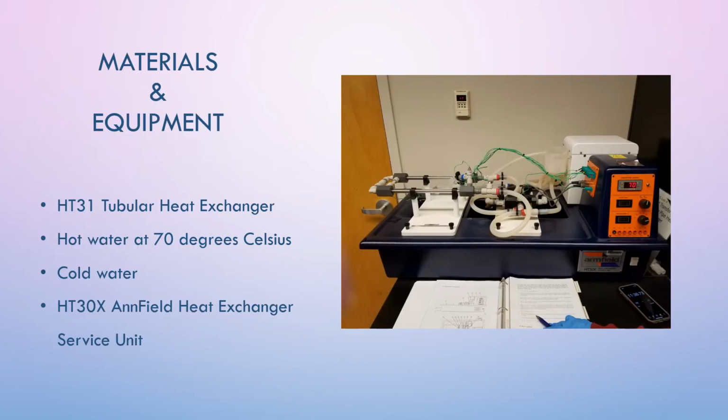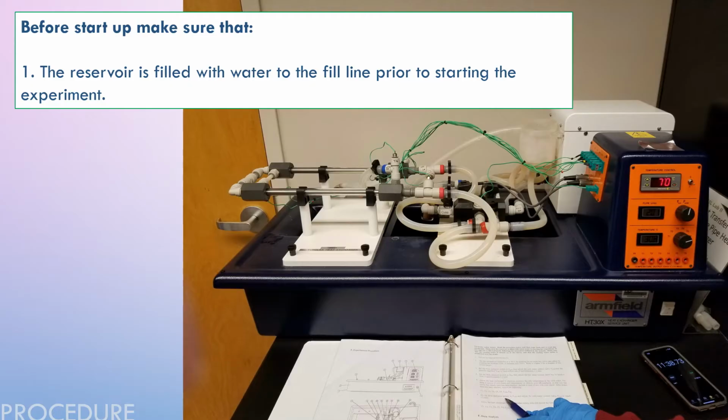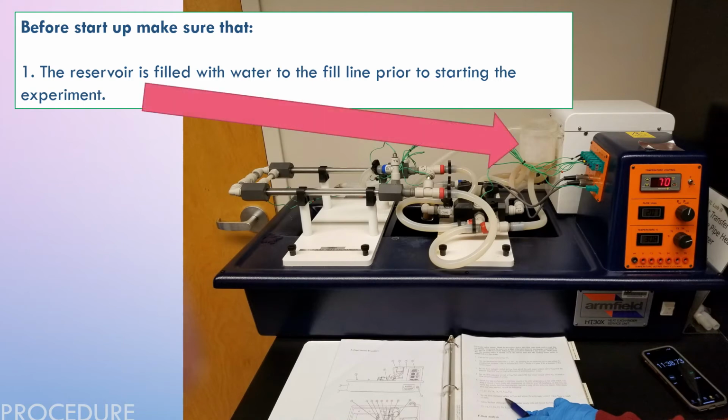Going over the materials and equipment of this lab, we used an HT31 tubular heat exchanger, as well as hot water and cold water for our process and our utility streams. An HT30X Anfield heat exchanger was used as our service unit. Before startup, make sure that the reservoir is filled with water to the fill line. You can find this reservoir right here, attached to the white box near the rear right of the unit.